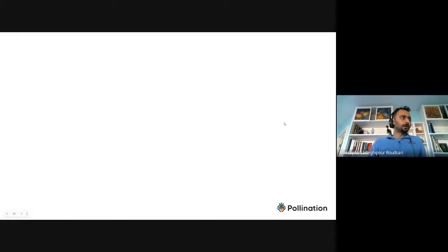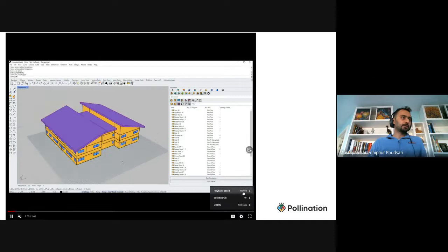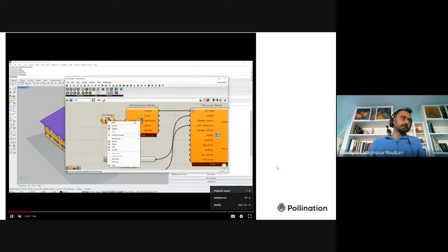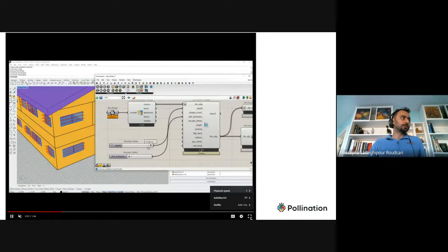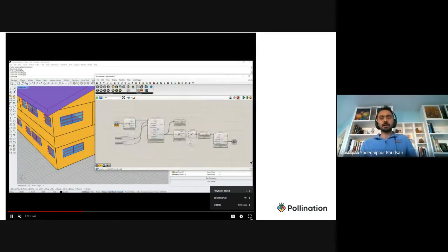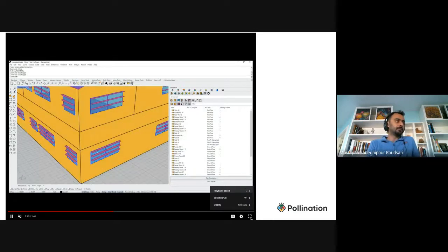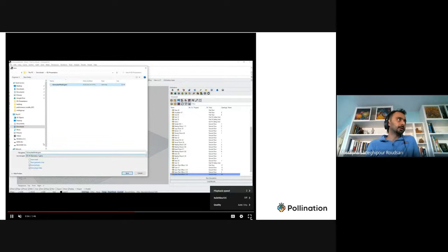Okay, then going back, last but not least, you can do the same thing going from Revit coming to Rhino, but this time you can use Grasshopper for a lot of automation stuff that is hard to do in other platforms. So in this case, I'm adding shade based on depth and distance. So I can take advantage of all the good things that Ladybug Tools provide. And in this case, I had to bake them back, but now we have the direct export to IES, so you don't even have to do this.